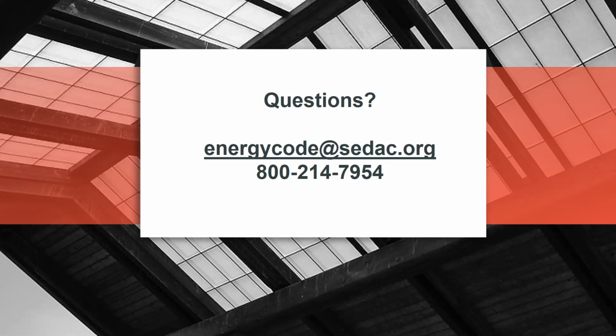Another one here is a question regarding compliance. Can a project comply with both ASHRAE 90.1 and the Illinois Energy Conservation Code, or does it have to be one or the other? Code compliance has to be shown via one method. However, code compliance is a minimum standard. So there's nothing that precludes a project. If a project wants to comply with the provisions of both the IECC and 90.1, that's perfectly acceptable.